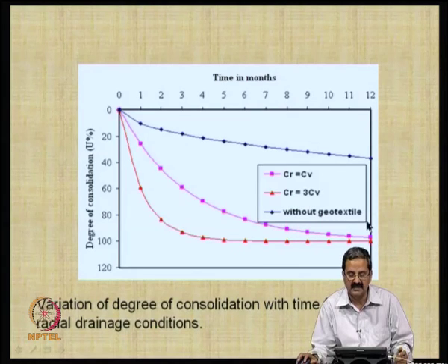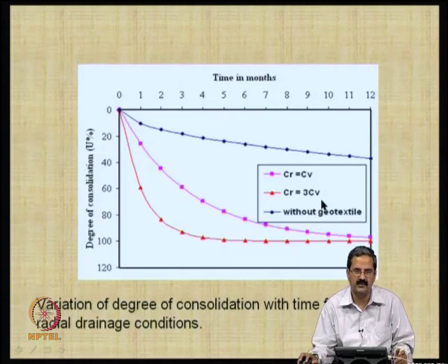But whereas, as I just mentioned, the vertical consolidation will be slightly smaller. So, you put that, I mean radial, and you see radial consolidation is higher than the vertical consolidation, normally 2 to 3 times, one can measure in the field. So, you can see that 100% is achieved within maybe 4-5 months, which is a very nice result actually, with